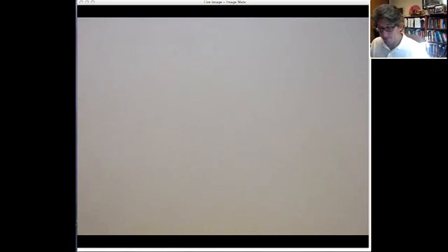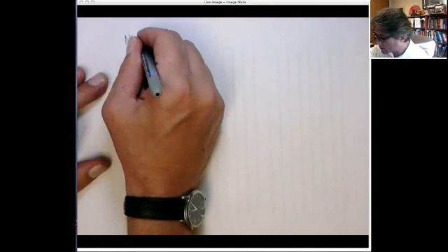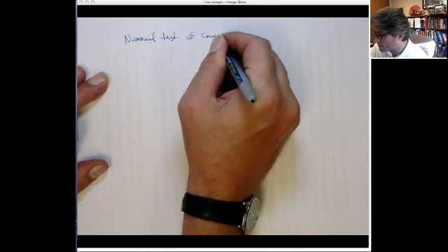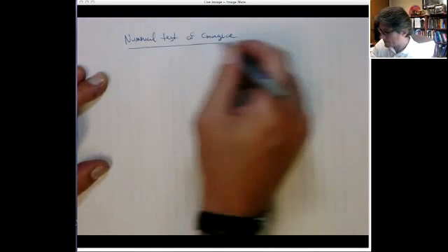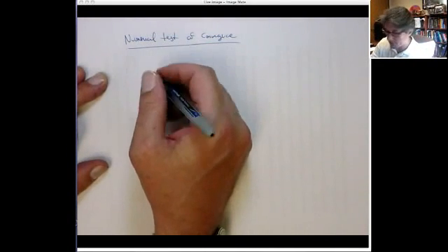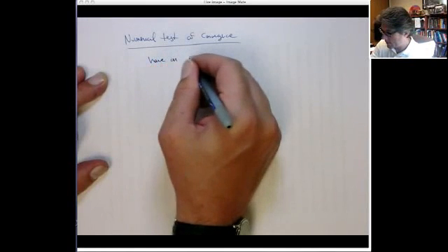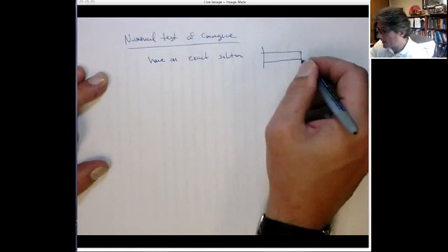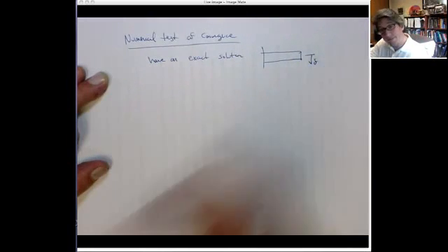Let me mention one other. So that's how you can theoretically estimate the convergence for your finite element mesh. Sometimes you have other reasons, maybe some new methods, or you have other things like contact, and you want to know the convergence. Well, you can always do a sort of a numerical test of convergence. So if you have some problem and you know an exact solution, let's say we have like a beam problem, and I know what the actual deflection is, right?